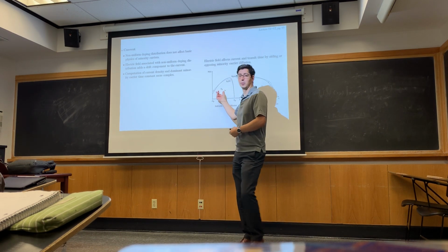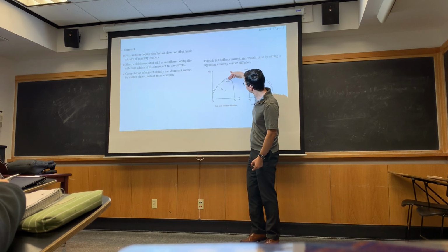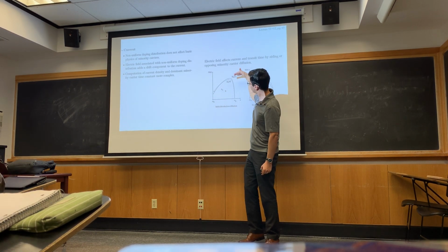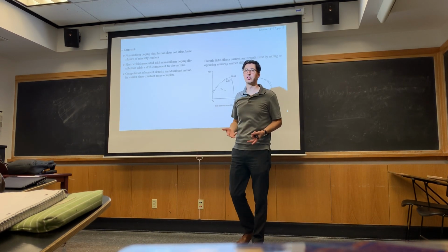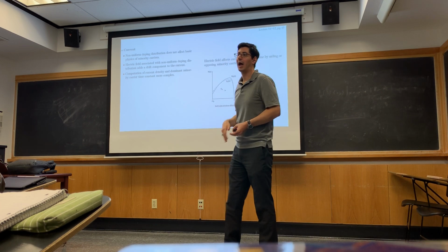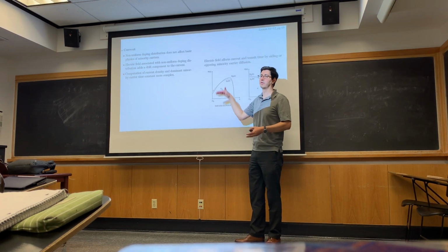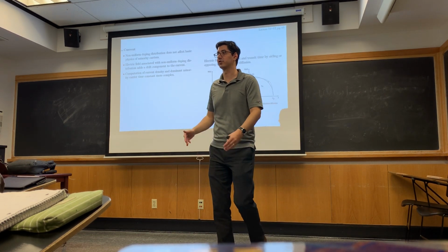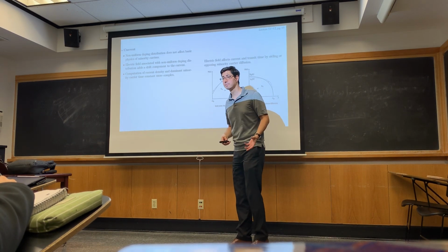Now there could be a small electric field. And in this case, if my minority carriers are diffusing this way, that electric field puts a force on electrons this way, so it increases the diffusion of electrons. It's not really increasing the diffusivity, it's just putting an electric field in the direction of diffusion, which overall makes it look like I have faster diffusion. I have a faster effective diffusion velocity. Does that make sense?